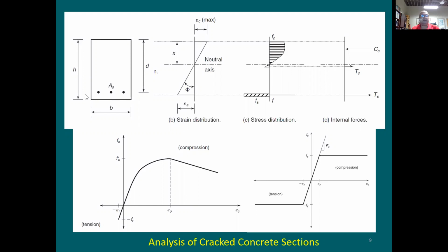How about the steel? Would you see here any stress in the steel or any tension in the steel? I'm gonna say yes. The strain in the steel is gonna be called here epsilon s. Now, if I know that this is gonna be here 0.003, do you know here the depth x of the neutral axis? Say no, I don't know it yet. But this is gonna be one of the variables that I'd like to work on.